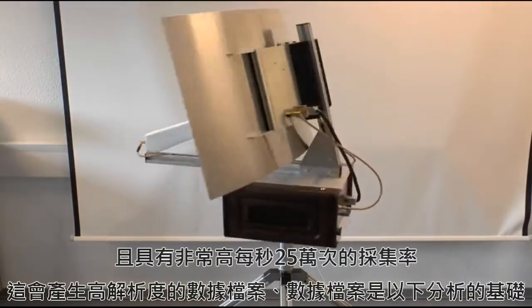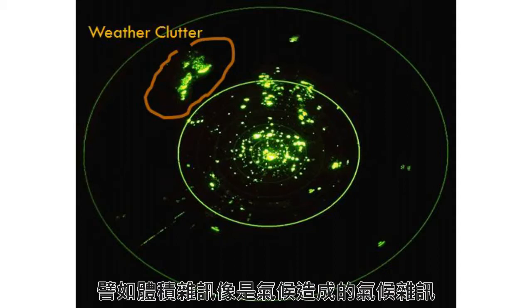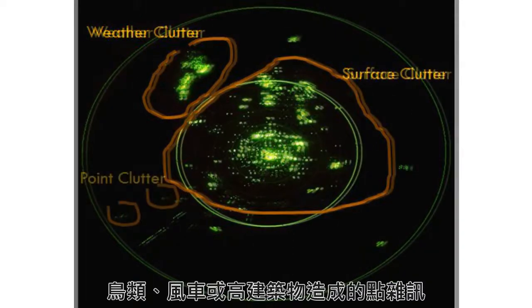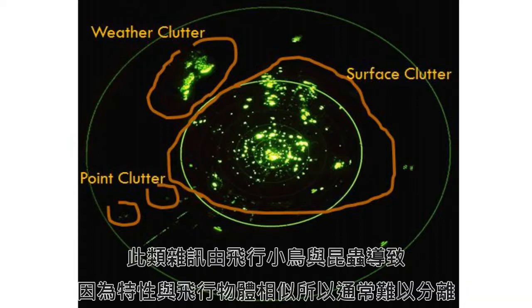There's a whole range of clutters that need our consideration. There is volume clutter, like weather or chaff. There is ground or sea returns, which we call surface clutter. There is point clutter, birds, windmills or individual tall buildings. Especially difficult to detect and to blind out are those which are called moving point clutter, sometimes also called angels.